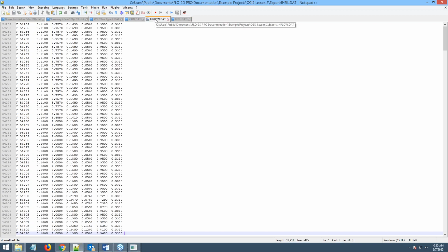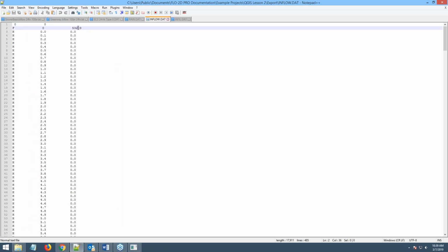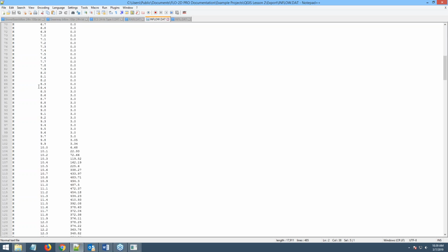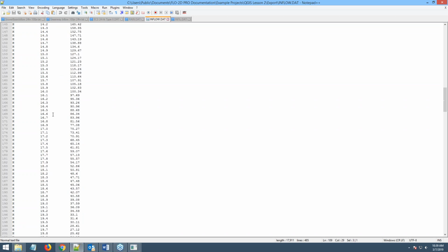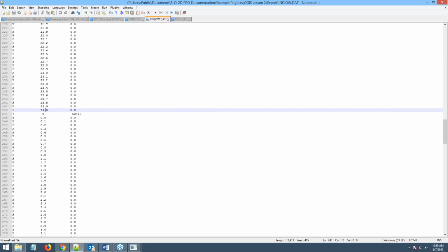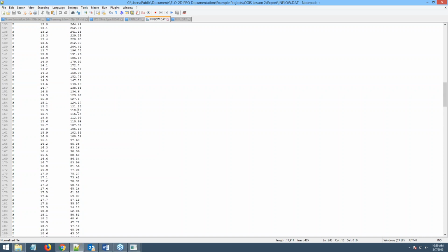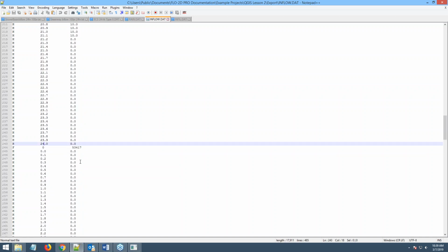Okay, also wanted to show you the inflow.dat. So here's your inflow.dat file. You see this is a floodplain node. That's the grid element number, and this is the hydrograph data. You can see that this is space delimited, not tab delimited, and it goes from 0 to 24 hours. And this is your hydrograph for that cell. Then you see that you have 2 of them.